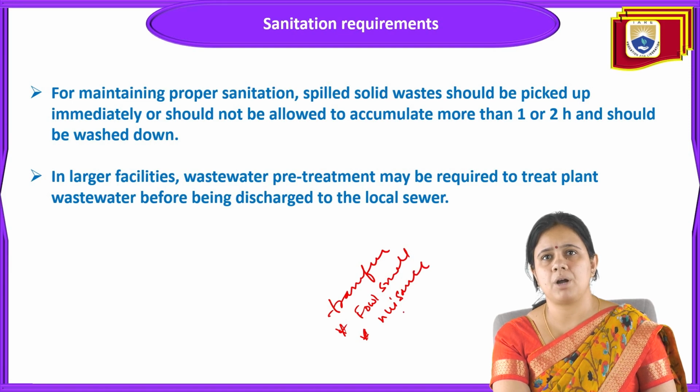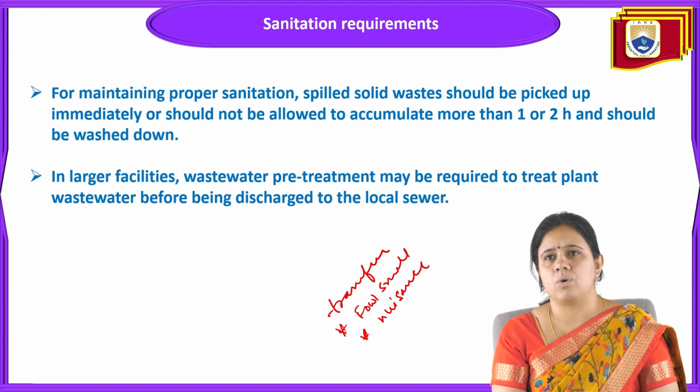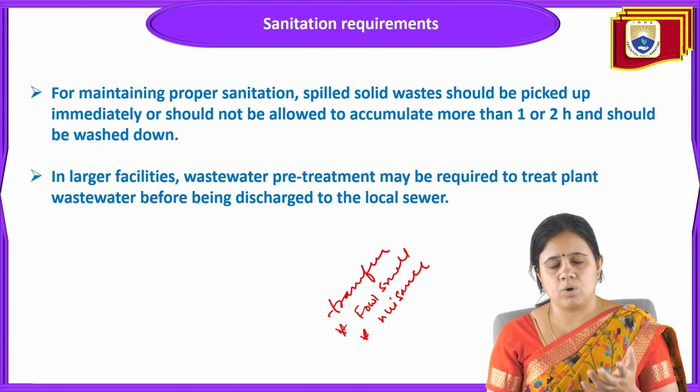So, for maintaining proper sanitation, spilled solid waste should be picked up immediately or should not be allowed to accumulate more than 1 or 2 hours and should be washed down. In larger facilities, wastewater pre-treatment may be required to treat plant wastewater before being discharged to the local sewer.